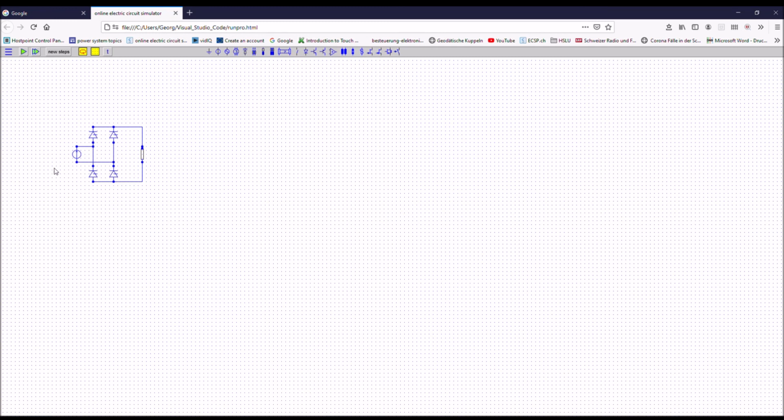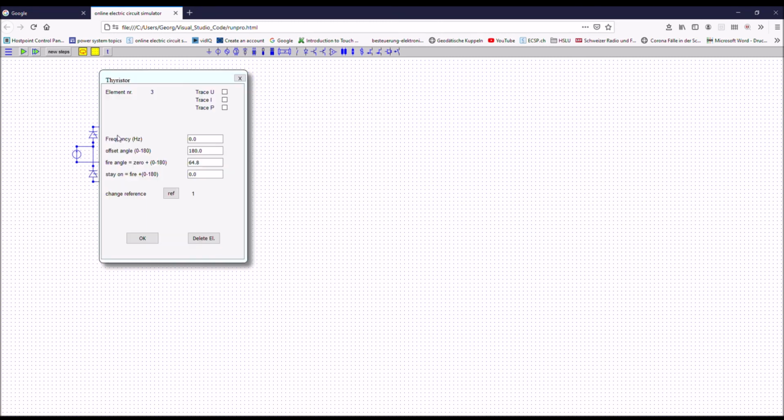And remember, we said that there is a delay of these 2 thyristors. Yes, this delay is important, otherwise you cannot control them on the same reference. In this case, without the delay angle, the result will be nil, because all the thyristors will just trigger on the positive half cycle, and therefore the arrangement will not work properly.